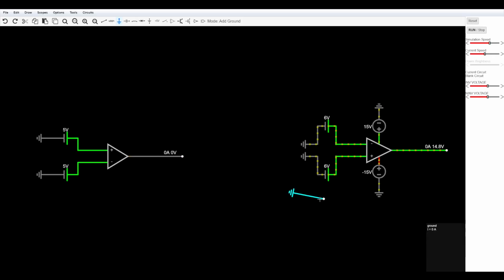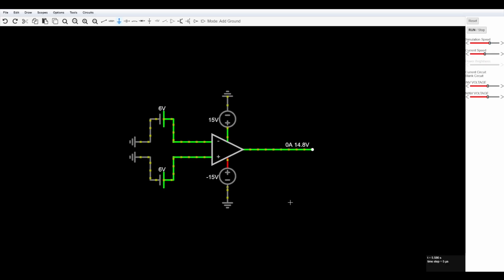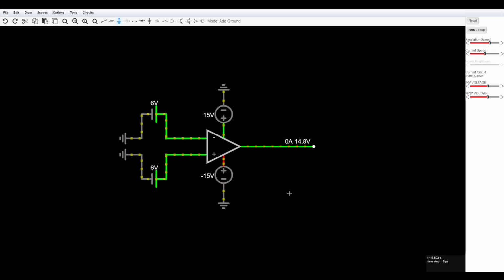Now over here we have a real model, which shows both 6 volts in there, and it's actually showing a positive voltage here, might be some kind of limitation of the simulator itself. Now in real life, these voltages would not be perfectly equal, so getting 0 volts out of here would be a little fussy, but you'll notice when we change it, it goes up, it goes negative.